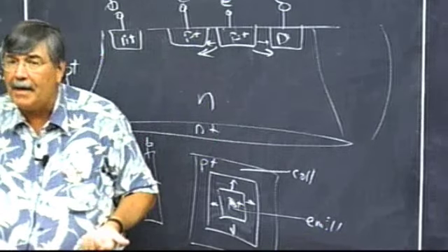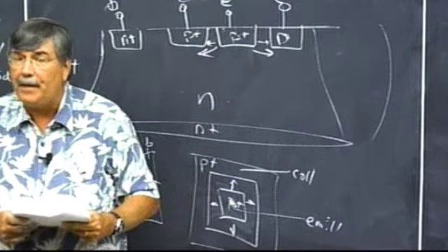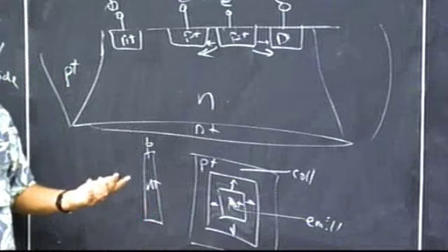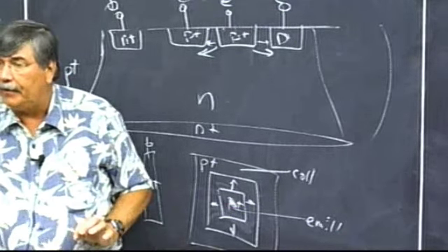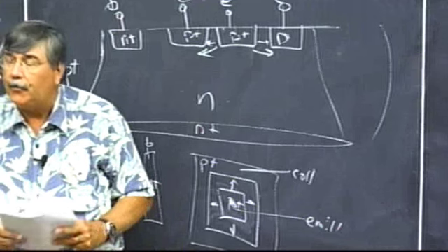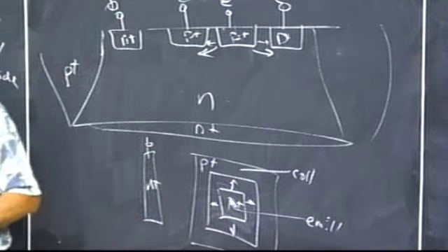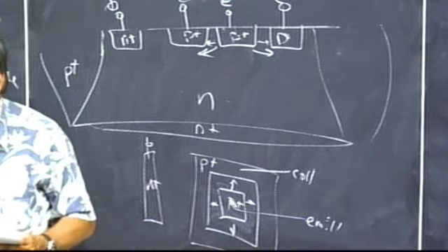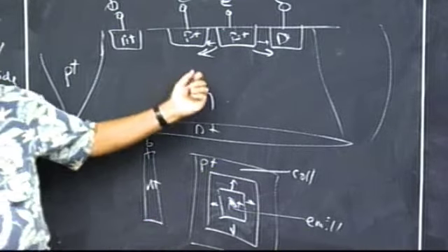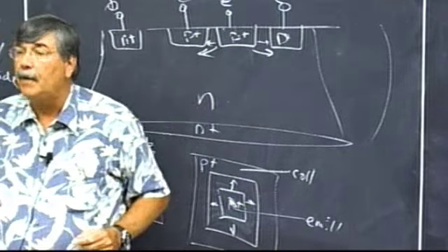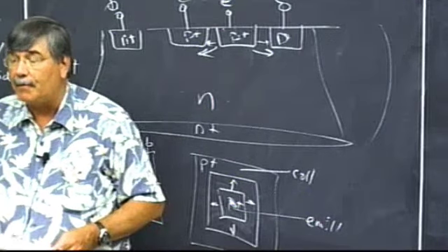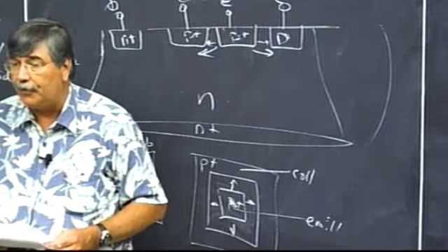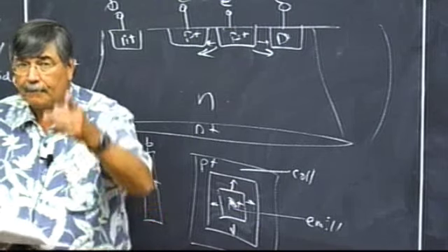So we get lousy betas. We haven't talked much about the speed of the transistor, but it's going to be lousy. These things are orders of magnitude worse than the corresponding NPNs. So a lot of early circuit designs, a lot of op-amps that you can still buy today, are still based on the assumption that the PNPs are awful, and the circuit designs are optimized. And we'll see that the circuit designs are optimized to take into account that the PNPs are just very poor quality. Question?